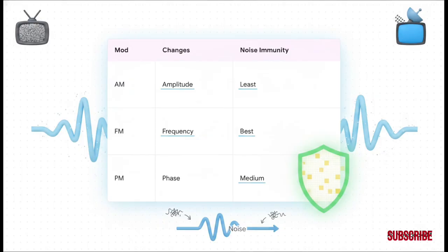But I want you to look closely at the noise immunity row. FM delivers the absolute best noise immunity, which is exactly why we use it for TV and FM sound transmission. AM, on the other hand, has the least noise immunity, so it's mostly relegated to older TV picture transmission, where static just shows up as a little visual snow rather than unbearable audio noise. PM sits right in the middle, and it is heavily utilized today in modern digital and TV communications.